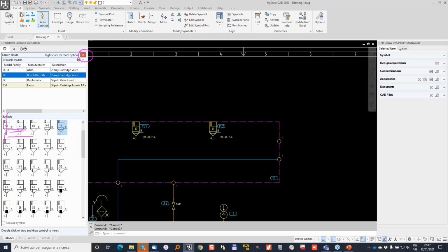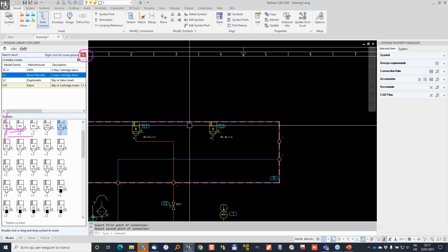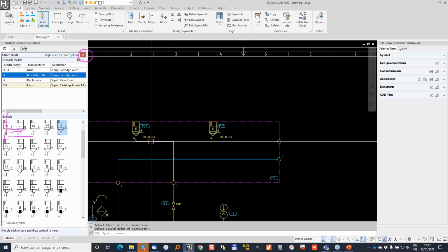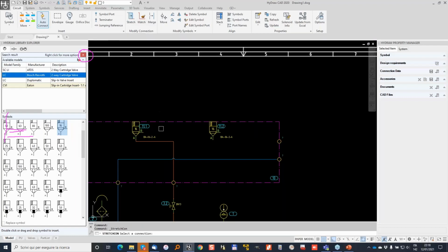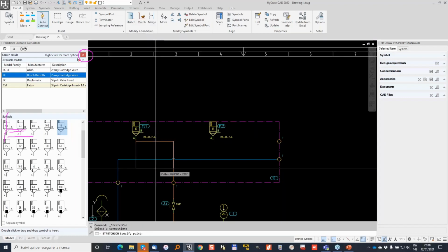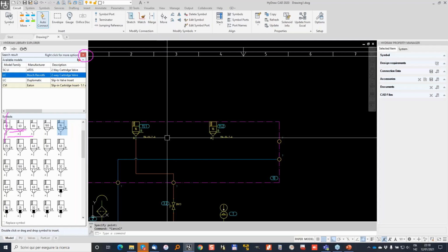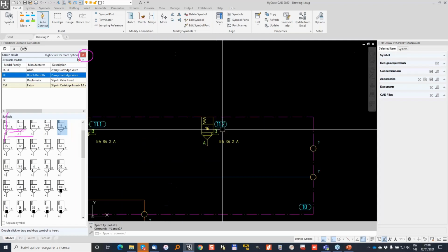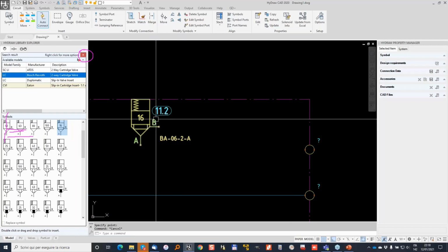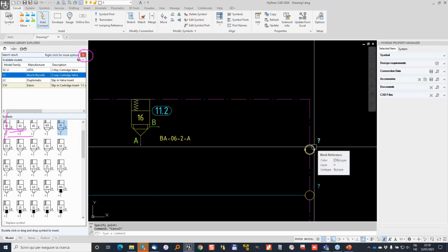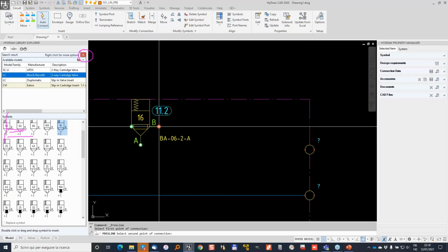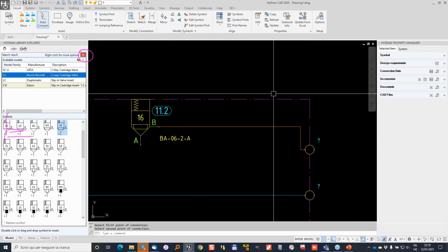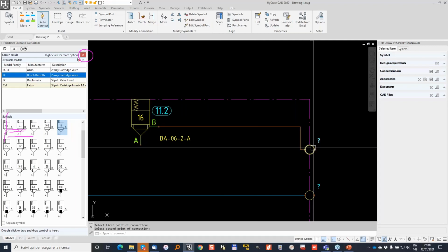I want to make a pressure line that starts from the pressure and goes to A. If you don't like the result of the connection, you can use the HyDraw stretch command, select the horizontal segment in this case and move it down. And now I want to connect directly the B port to the exit here. Of course, we can make the connection pressure from B to A. And we can also align these two ports.